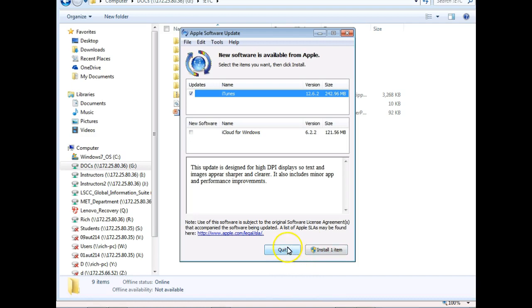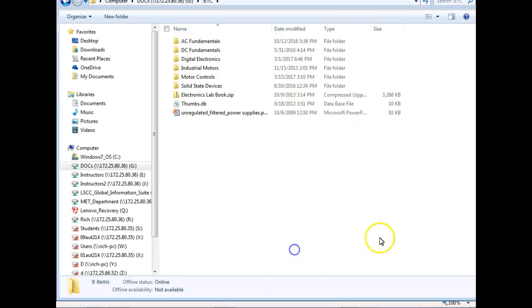Yes, and what people don't understand is that's without the tool attached. So that's the lifting capacity or the moving capacity of the robot. If it's got a payload of 500 pounds, and you put a 100-pound tool on there, you can only pick up 400 more pounds, right?